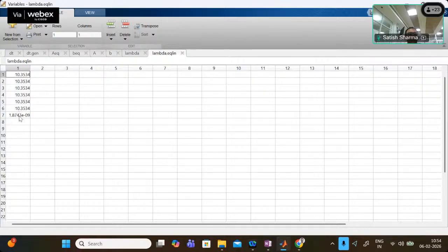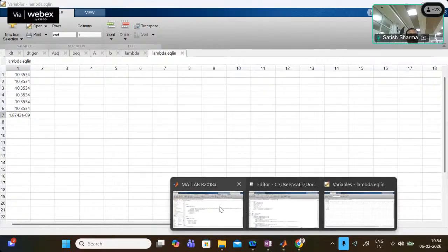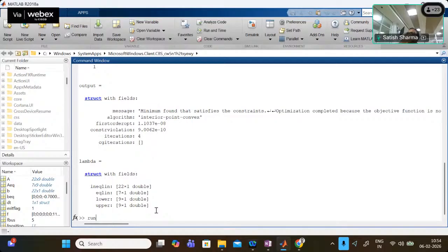Okay. So now the question is, how do we know that whatever we have written is perfect or not? That is a very important question. How will we be sure that whatever we have obtained here is the true values? For that, I asked you to install MATPOWER. Once MATPOWER is here, there are direct commands for these existing cases, where you can easily solve these OPF and DC OPF and power flow.